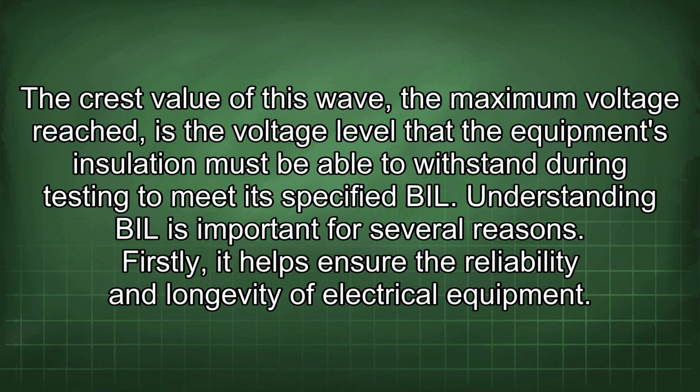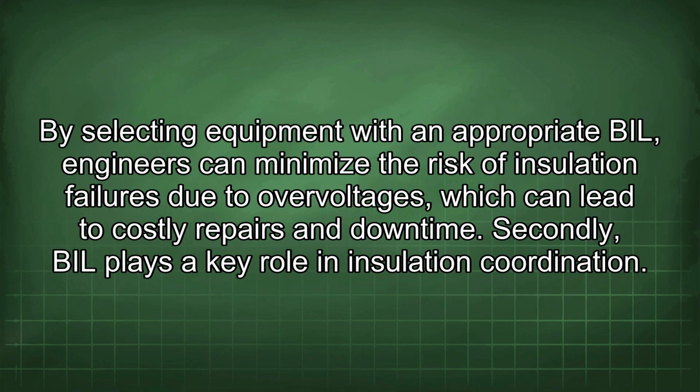Understanding BIL is important for several reasons. Firstly, it helps ensure the reliability and longevity of electrical equipment. By selecting equipment with an appropriate BIL, engineers can minimize the risk of insulation failures due to overvoltages, which can lead to costly repairs and downtime.